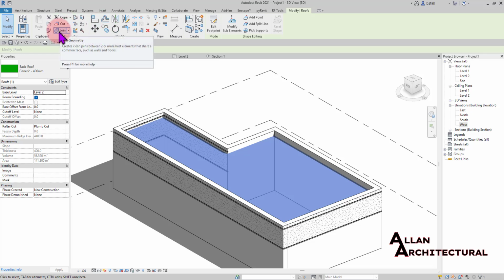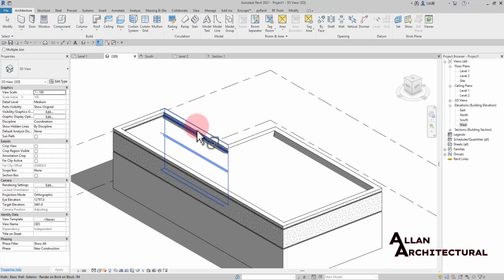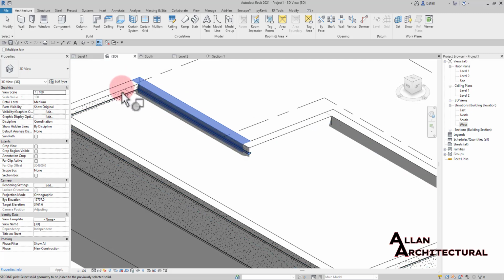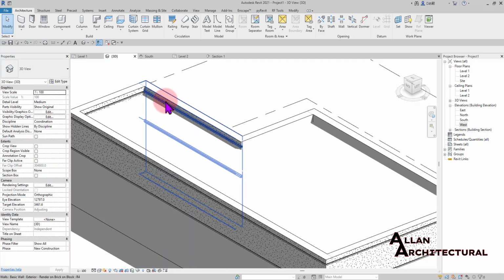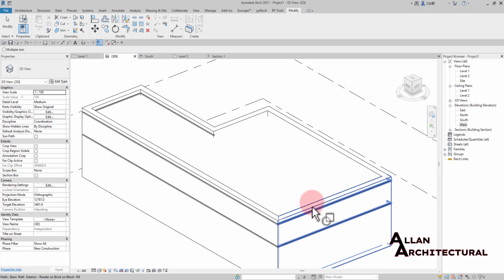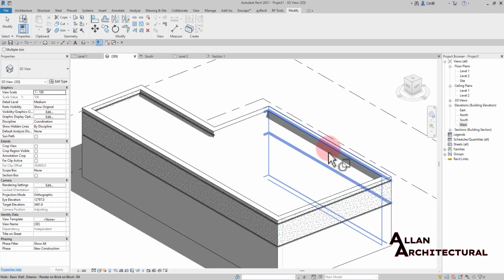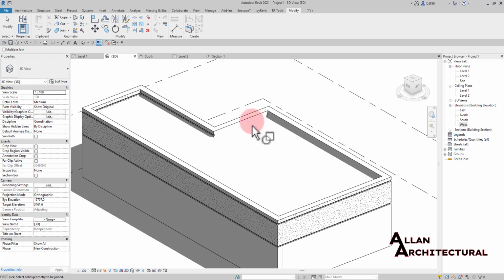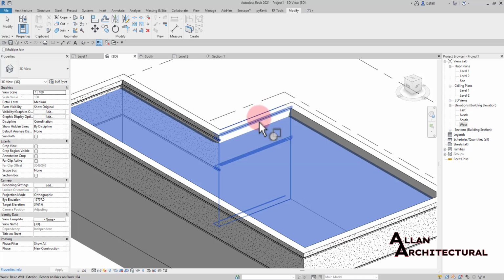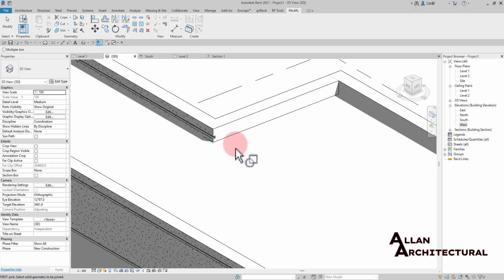All right, so you just have to click on that join tool, hit the tab key, and then you join that to that roof as well. So you need to make sure you join. Just escape out of there, head into your modify tab, select the join tool, and then make sure you select that roof you want to join. Hit the tab key, make sure you select that roof, and when that roof is selected, you can join that to that wall.